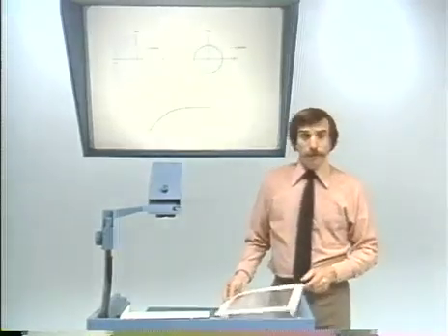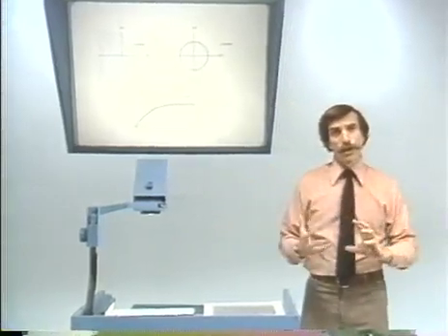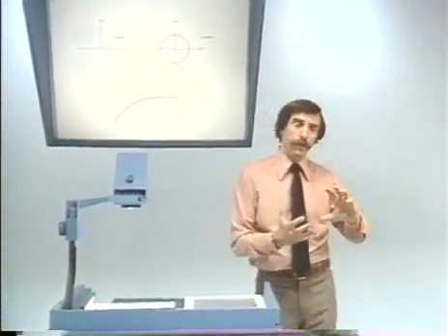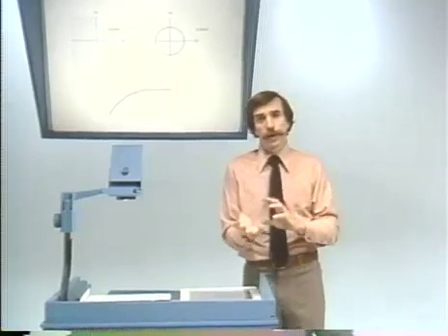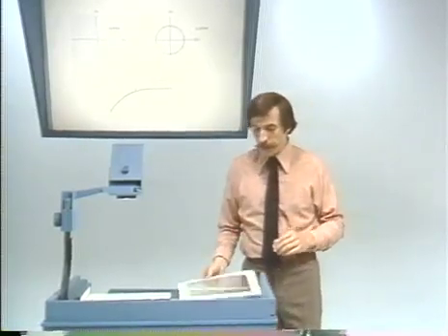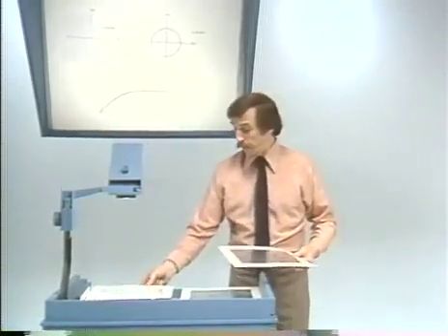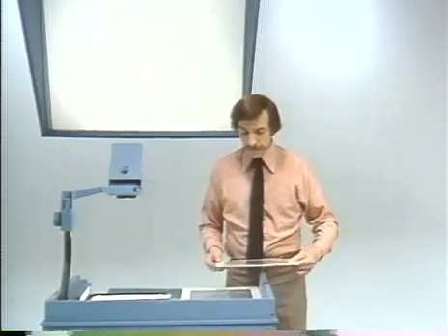All right, now that means that there is a nonlinear distortion of the frequency axis if we were to take a continuous time filter and convert it to a discrete time filter with the bilinear transformation. How do we account for that, or for that matter, when can we really use it?